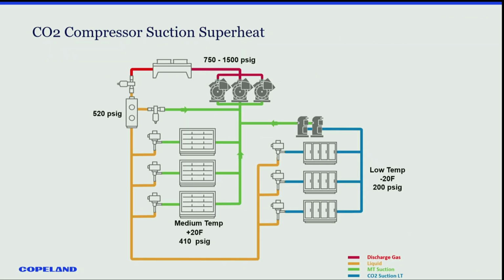So I talked about superheat, which is one thing I want to make sure that we cover. On HFC compressors, you've probably been hearing your entire career that 20 degrees superheat is the norm. And it is for the medium temp. It's around 20 degrees, 18 degrees, or 10K. 10K is 10 degrees Kelvin. You'll hear that a lot. And on low temp, though, it's 36 degrees.